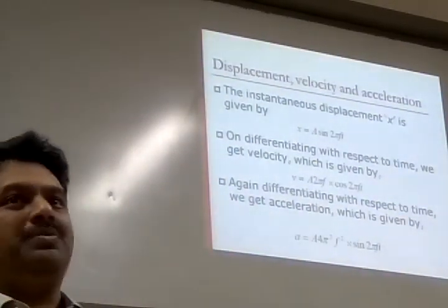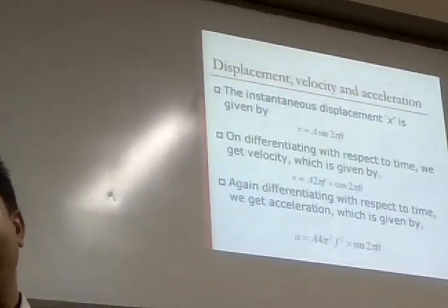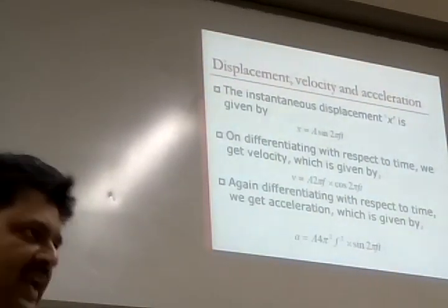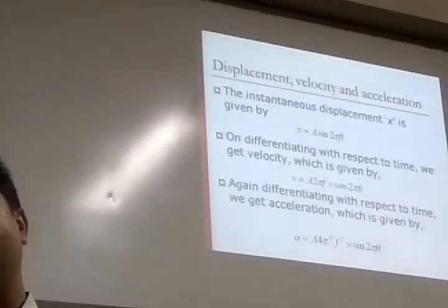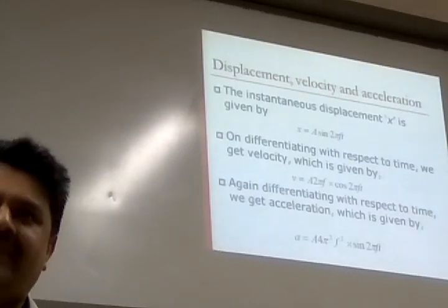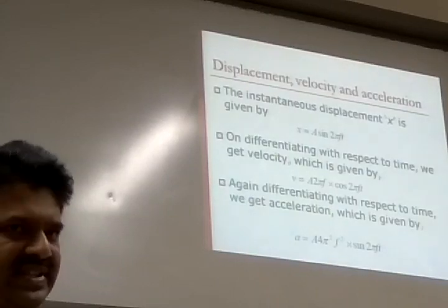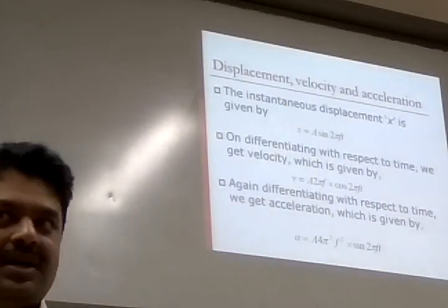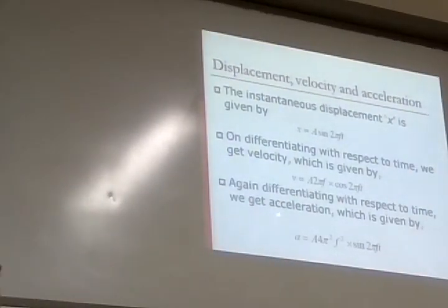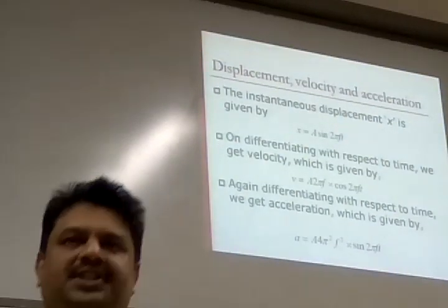400 times I will show the output. Very exaggerated output I will show. So that it will be useful whenever I have some high frequency signals that I am interested in. Mostly we are interested in high frequency signals, not low frequency signals. Whenever I am interested in high frequency signals, I am least bothered about the low frequency signals. If the application is like this, then the best parameter to measure in vibration is acceleration. The best parameter that we measure is acceleration.